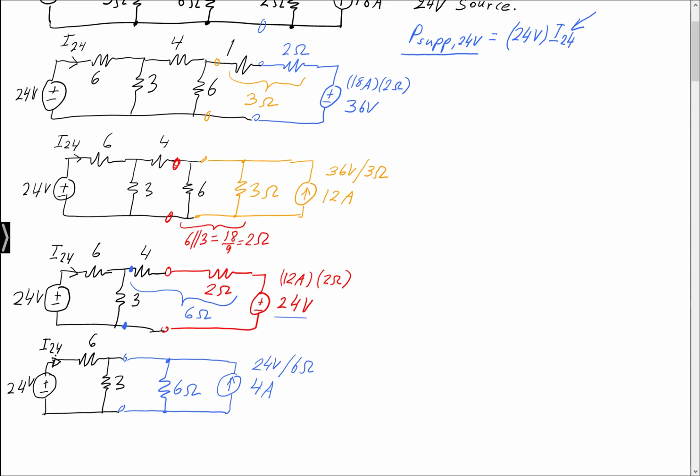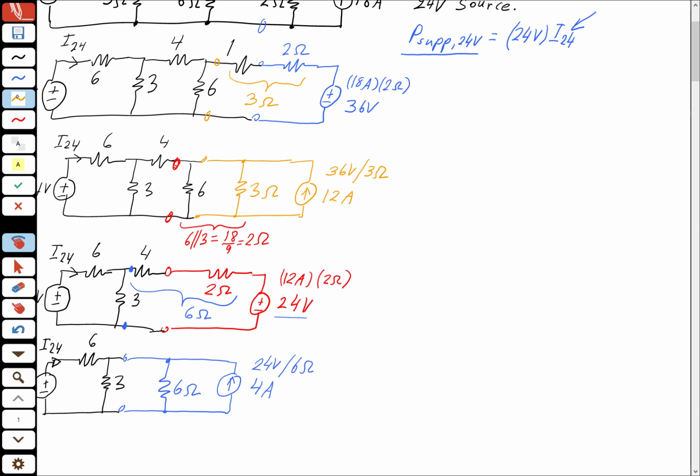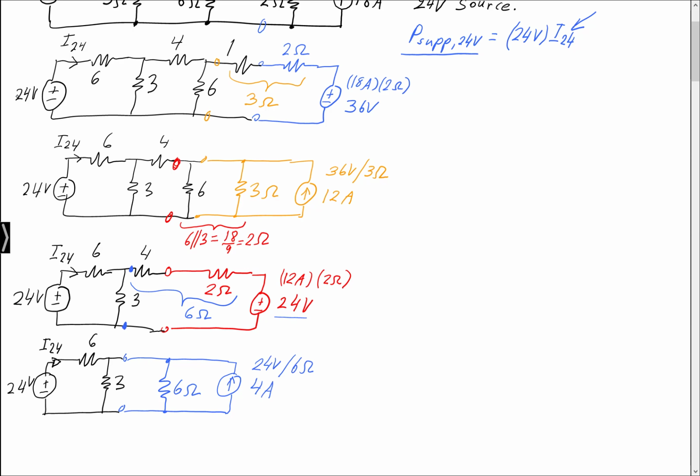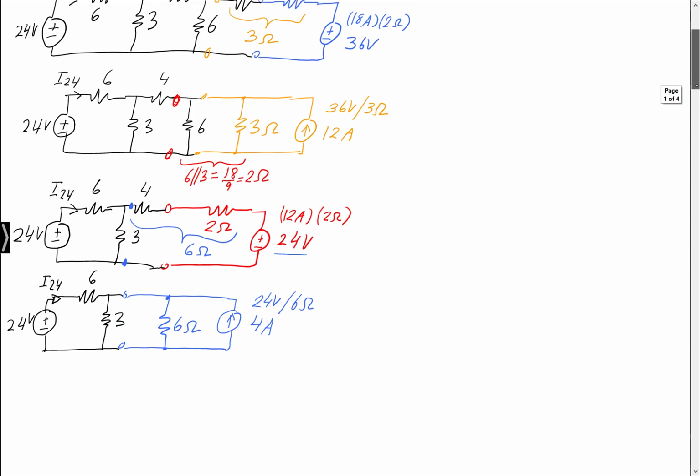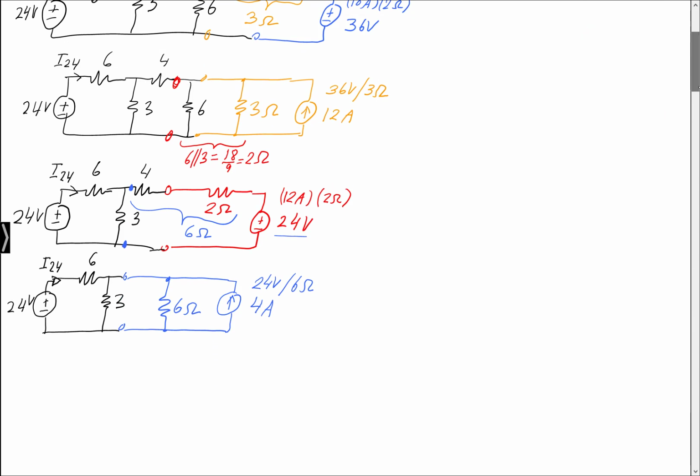Okay, what do I see here? Well, I don't have to tell you how this goes, but you can kind of see the pattern here, and it's good to understand the pattern, what we kind of expect out of here. These two resistors here are in parallel. So I have 3 parallel 6. We've seen this before. This is simply 2 ohms.